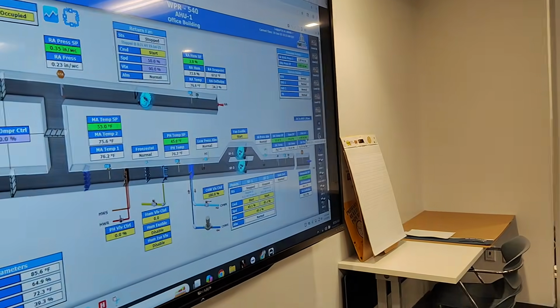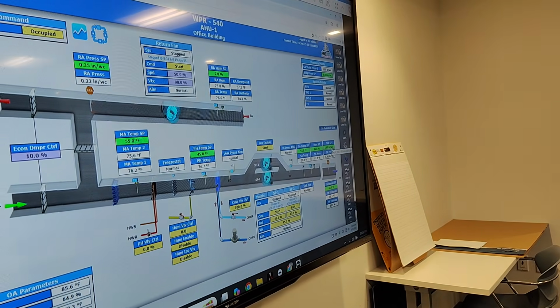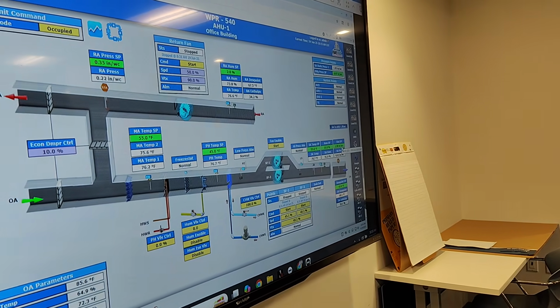And it appears to be listening. It's just doing a crummy job of it. You know, it's just not doing a good job of it. So it does seem to be ramping that fan now. It's just taking forever to get there. And you're still looking at, what is that, 0.3 inches? No, 0.35. 0.41. Okay, so right now you have not even a half an inch of pressure in the